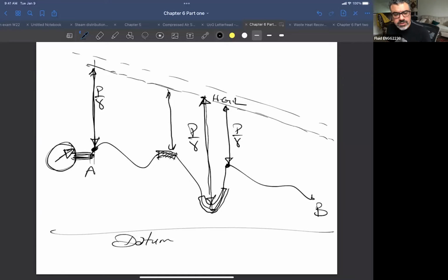So not necessarily is the pressure at the pump the highest point. It all depends on the topography of the land, how the pipes are laid around this topography. So at some points you might see pressure values that are even higher than the point at the first point of the pump, right? So in order to do this, you need to find the pressure distribution, or plot the hydraulic gradient line that we covered in chapter 5, I guess. Okay.